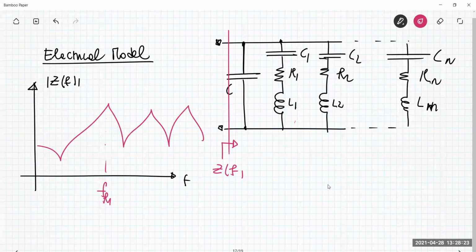But anyway, that's a typical application for an actuator. Of course, the piezoelectric material can find a very wide range of applications, but in order to use them as mechanical actuators, if you drive that piezo material with a source, using a driving frequency which is less than the first resonance here, F0, then the behavior is simply that of a single capacitor.